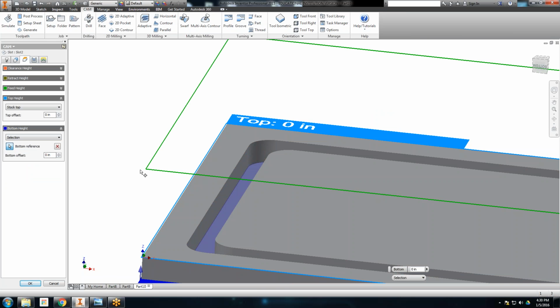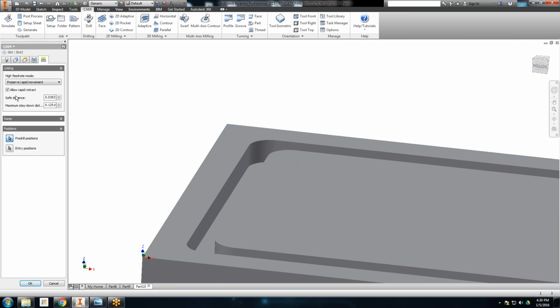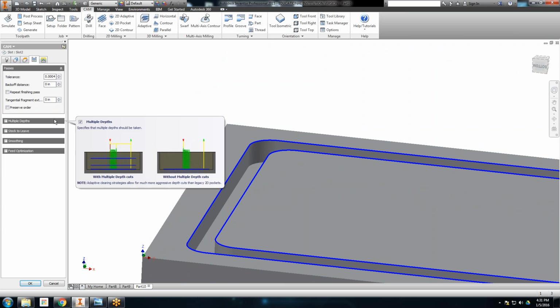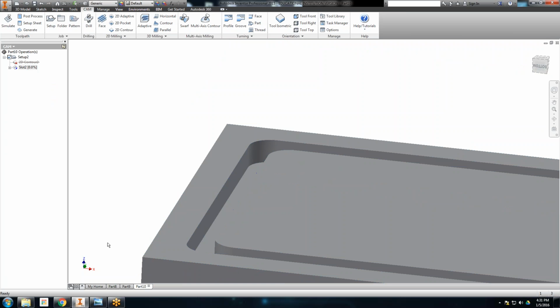Most pockets don't like that. There's no tolerance. Gotcha. So when the tool's going in there, there are a lot of times that it just won't do it. It says that it's not physically possible for an 1/8 inch tool to make an 1/8 inch groove just because there's no room for a pocket. So then you'd end up having to use a really small bit, I guess, and then it would take forever. Yep.